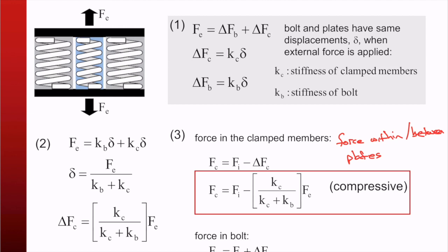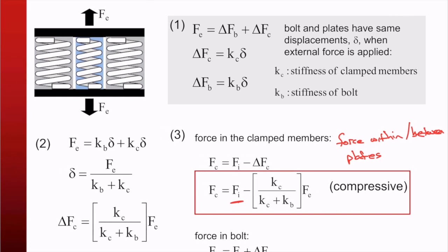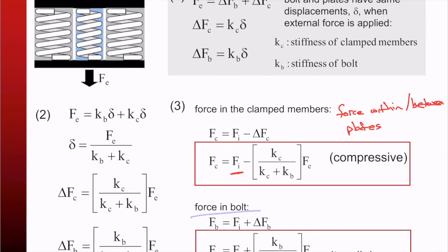That's the initial load, whatever it is, minus the plate's share of the external load I apply. Similarly, the force in the bolt here is the initial tension plus the bolt's share of the external load.